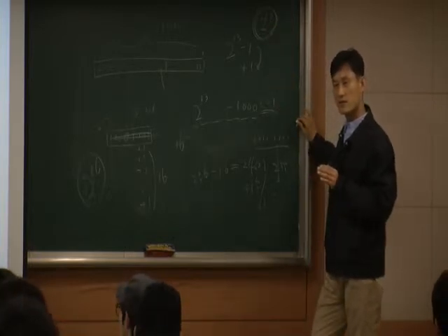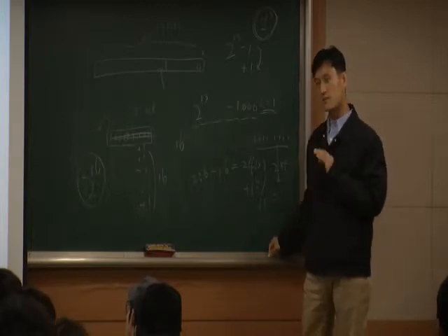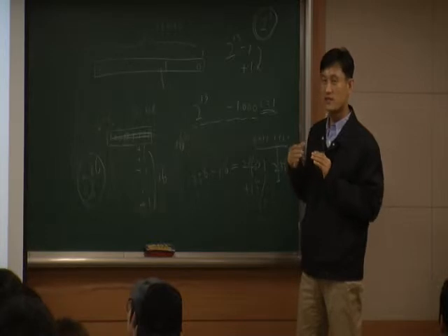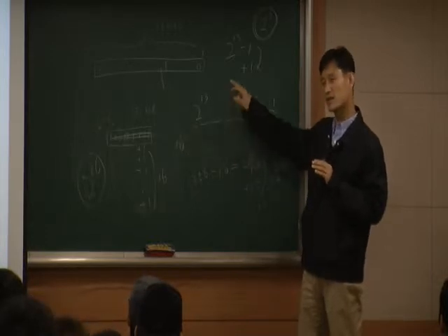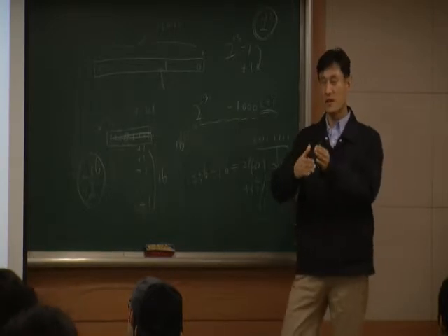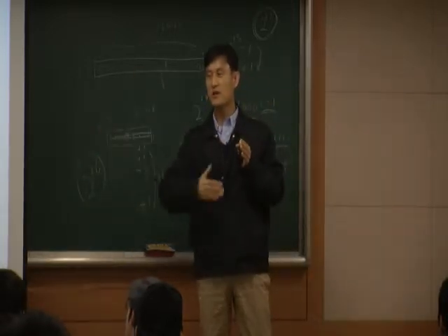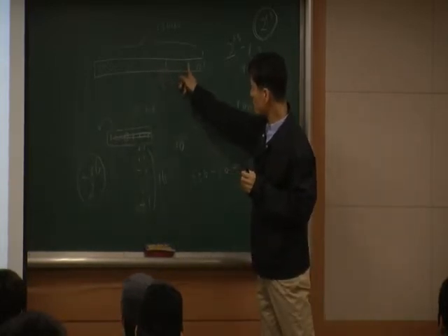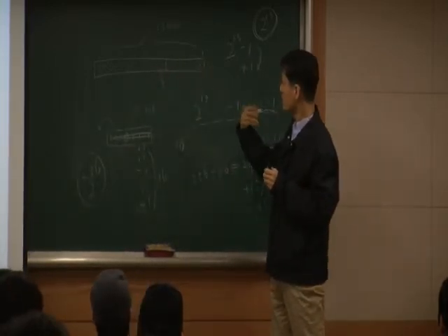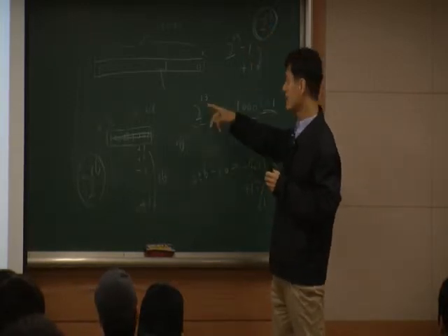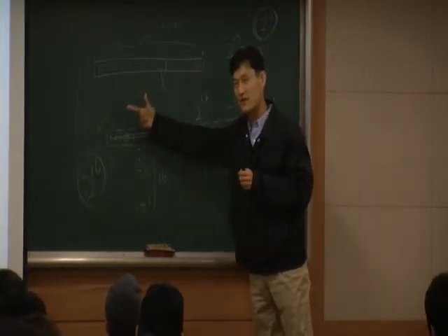Do you understand what I'm saying? In that case, it's not 1 millisecond, right? Maybe only the first time it was 1 millisecond, because at that time I programmed this one as the initial value. But 1 millisecond of delay only happens the first time. On the second time, it's going to be a lot more delay, because it starts from all 0, right? And you're going to count these many, 8K, of delay. Only then will it become another carry.